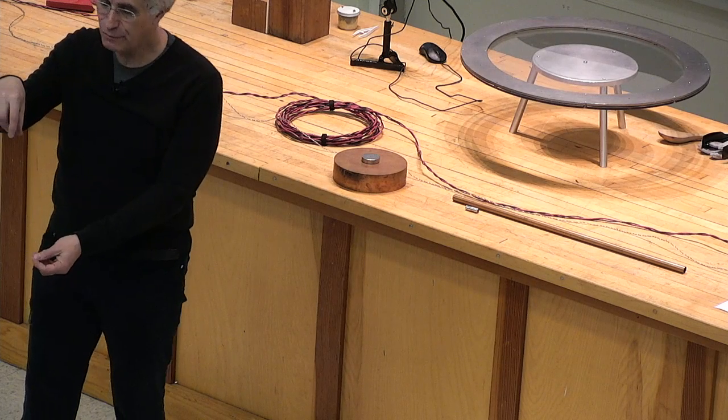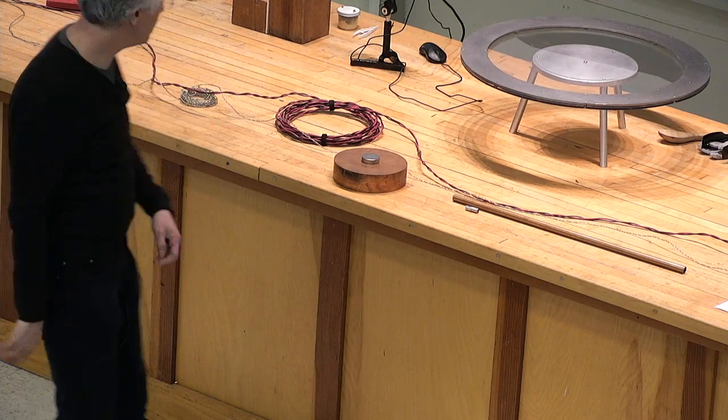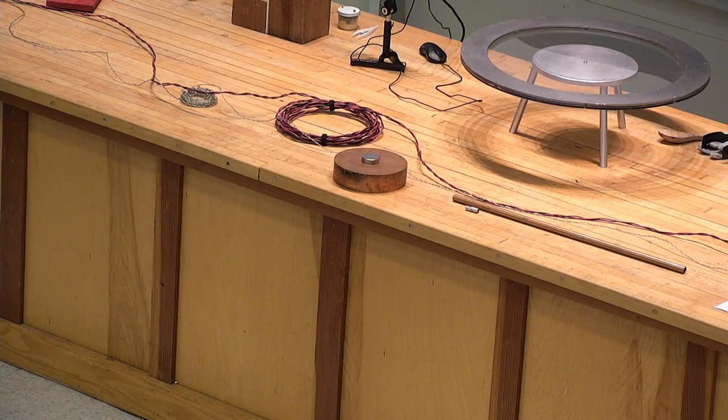Well, if you look at the forces on those two parts of that iron piece, and let me just hold it here, this will be my iron piece. And it's partway in the coil. The coil's up here, and this guy's dangling out the bottom. They both will develop poles, and the poles will be of equal strength and opposite. One will be north, one will be south, because this has to retain its zero net pole. But this pole, being in a strong part of the field, will be pushed on harder by the magnetic field than this guy. This guy's out in nothing interesting land. So this guy gets the biggest force.